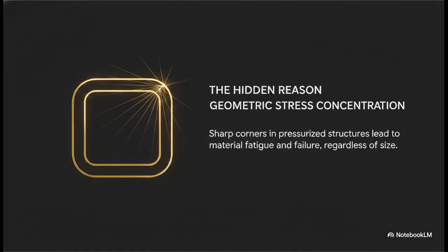So let's clear something up, because it's absolutely crucial. It is a major misconception to claim that an ordinary passenger window caused every single Comet failure. The forward escape hatch and the roof-mounted ADF windows were the actual failure points in the water tank and Elba incidents, respectively. The catastrophic flaw wasn't one specific window. It was the systemic engineering geometry of the aircraft. The underlying problem was the presence of sharp, squarish corners anywhere in a repeatedly pressurized metal structure.